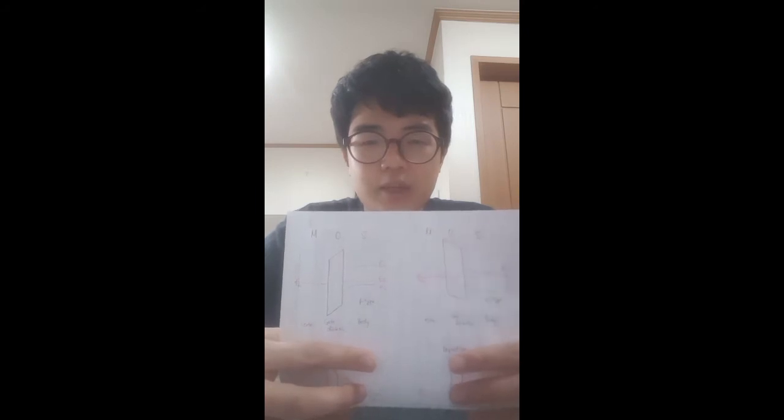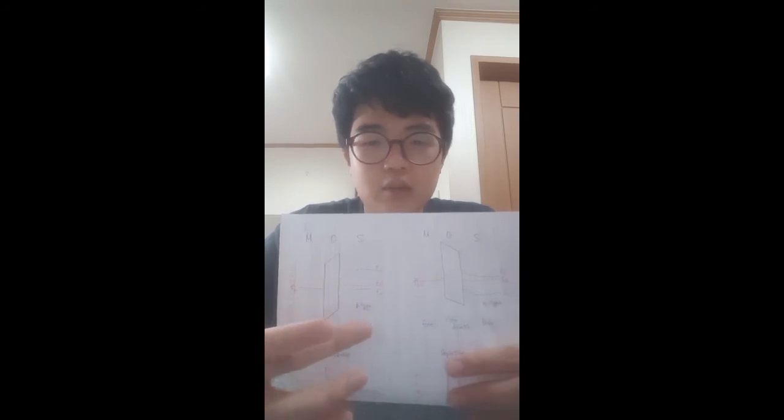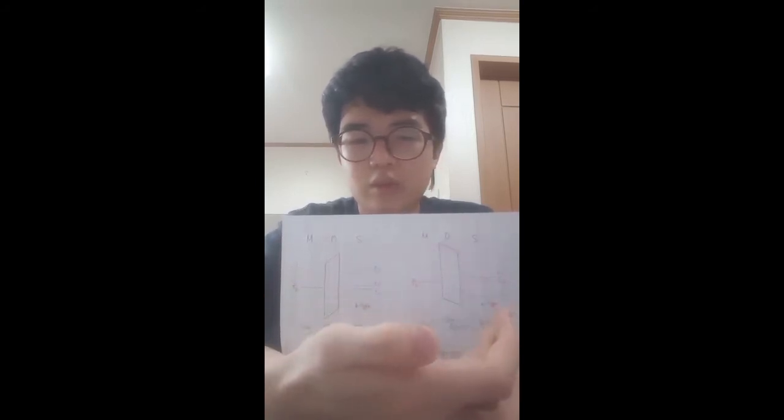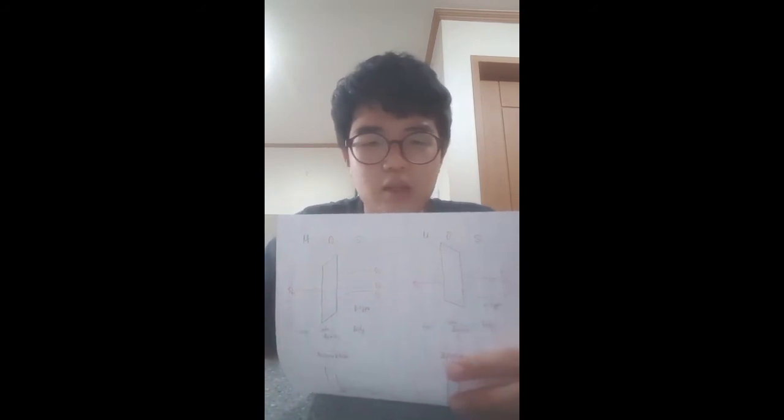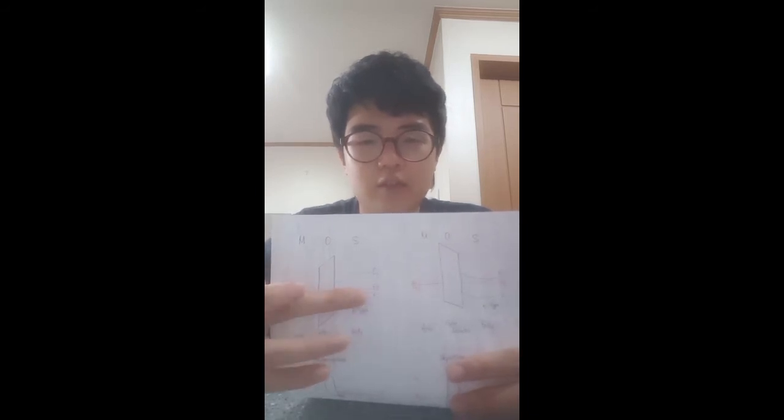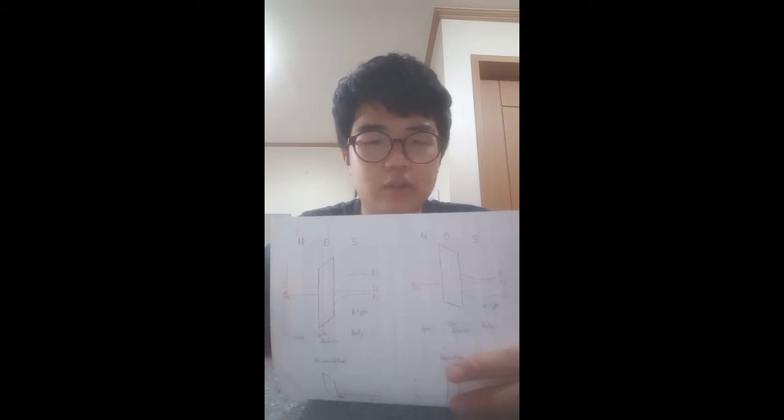These two different energy band diagrams are for MOS capacitors which use a P-type semiconductor or an N-type semiconductor. Same as the PN junction diode and Schottky diode, to express the thermal equilibrium condition, we should draw the metal's work function and the Fermi level constant. Because of the characteristic of metal, which is called equipotential, we should always draw the metal's work function constant.